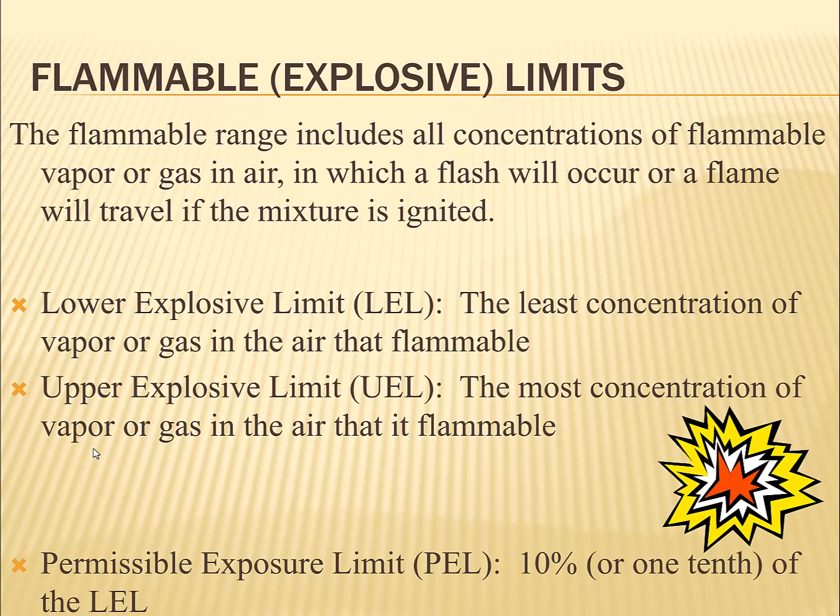And so what OSHA says is you can't work anywhere near. You can't work above the upper explosive limit, but you can't work just below the lower explosive limit either. They want you to work way below the lower explosive limit. And that is what they call, down at the bottom, you see the last bullet, the permissible exposure limit, PEL. So Pell, like a Pell Grant. Well, not a Pell Grant, but anyways, maybe it'll help you remember it.